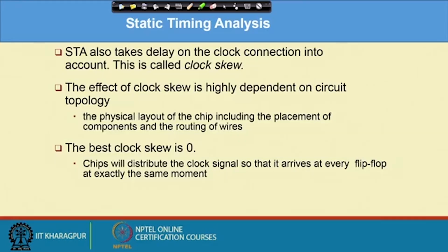So, this is the concept of this timing analysis, static timing analysis. Okay. And this clock skew is an important factor, not only clock skew, but also setup time, then clock to Q, then this T logic. So, during optimization, what we have done till now on the combinatorial logic part is reduction of the timing or reduction of the area on those particular paths, but we have not considered the other things which are associated with the whole timing closure calculation. So, that we will see in continuation of these lectures.